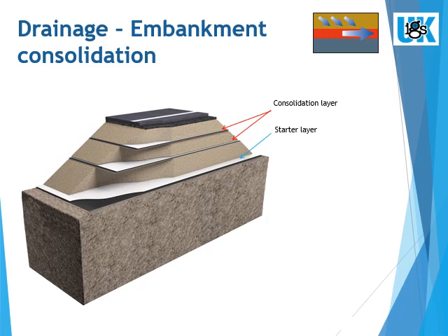Whilst the starter layer takes away the water from the base, you still have to wait for the rest of the embankment to consolidate under its own weight. The problem is, this often takes a long time, maybe up to 2 years on some projects. The water between the particles, once again, caused the problem because the voids are so small. This often means the whole site program is dictated by the earthworks consolidation rate.